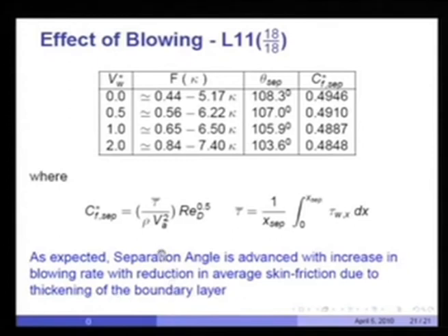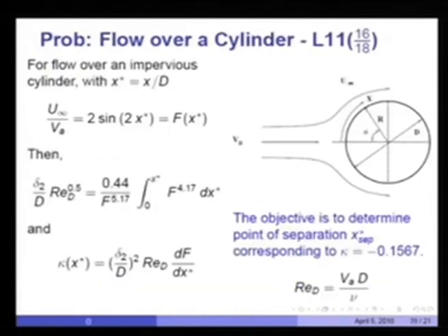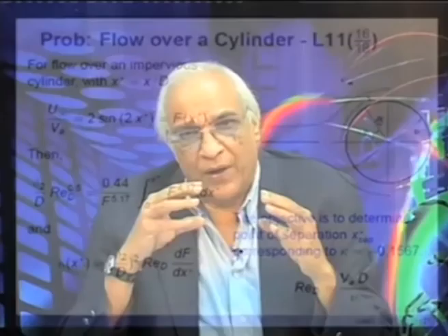This shows you the power of the integral method. Of course, what it cannot do is go beyond the point of separation and complete the analysis of flow over a cylinder, but nonetheless, it is a very useful tool to determine flow through convergent or divergent nozzles. For example, where the free stream velocity would either accelerate or decelerate with x, and you want to determine the thickness of the boundary layers developing on the wall, because it is this thickness which determines the discharge coefficients of such nozzles.